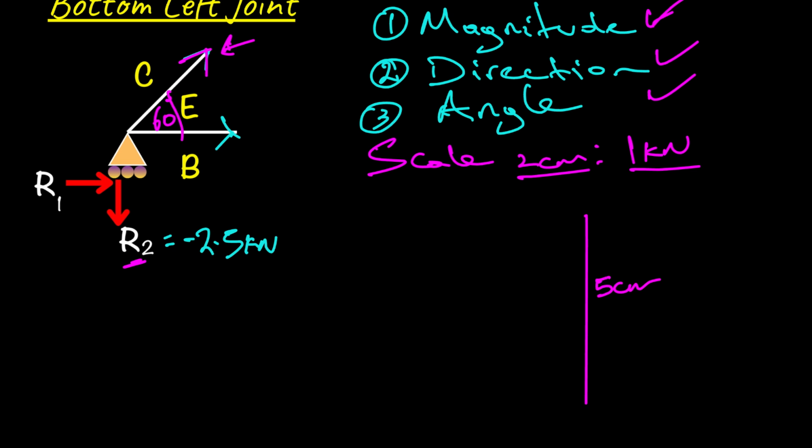So what's happening now is I'm going to try to connect the other two parts. You are going to draw a lot of reference lines actually. The first line I'm going to connect to this is the horizontal member, BE. So that's going to be going across like so. That's my horizontal member. Notice I am not too fussed about the length of it at this point. The good thing is you know what that line measures, which is your 5 centimeters, so that's critical.